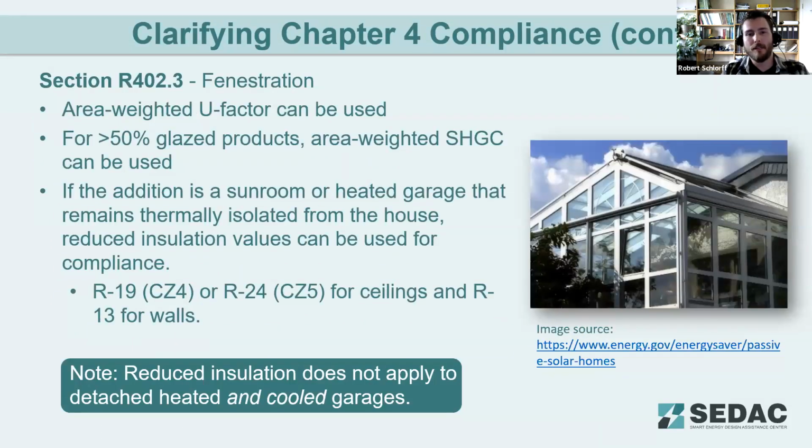Clarifying chapter 4 compliance continued here. So looking a little bit more at fenestration, section R402.3, the area weighted U factor can be used to determine compliance for fenestration. For buildings that are greater than 50% glazed, you use the area weighted solar heat gain coefficient.